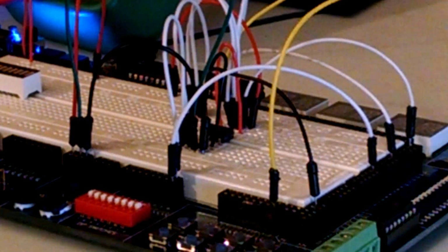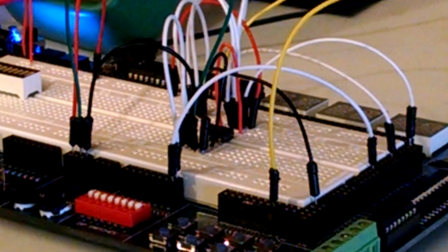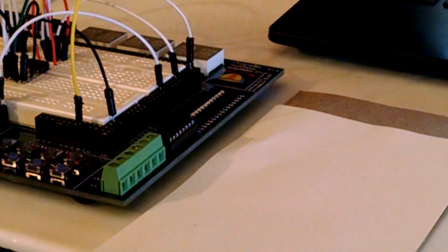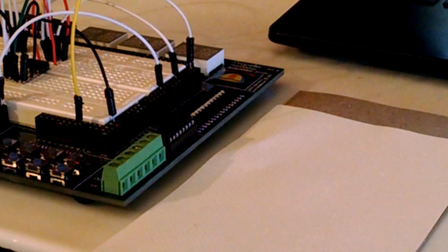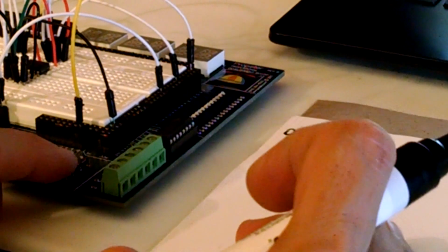Now the ADC has a volts measurement stored in its memory register, which we're going to retrieve as a binary number. Notice that the data pin is low. This is a null bit. Now let's send the next clock pulse in order to get the first bit of our number. Our data LED is off, which means 0, so we mark it as a 0. Let's do the next one.